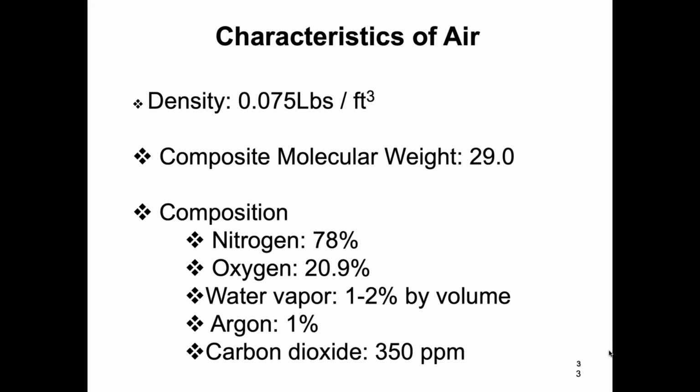The speed the air is moving at and the amount of air we're moving has to do with how much work we're doing, how much energy we're expending. That has to do with the density of the air, the velocity, the size of the ductwork, the frictional forces, heat, and so on and so forth that's generated in the process. So all of that ties in.